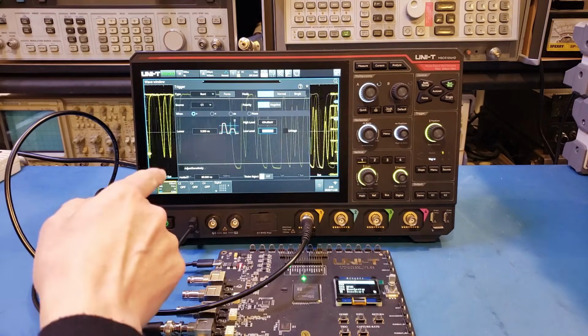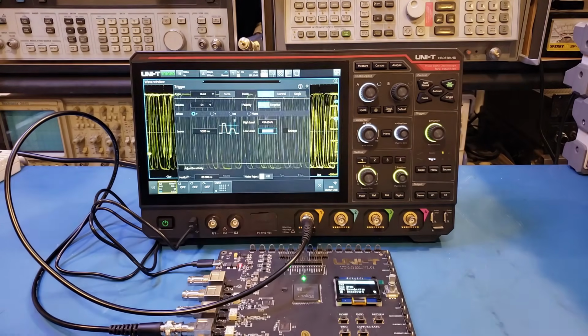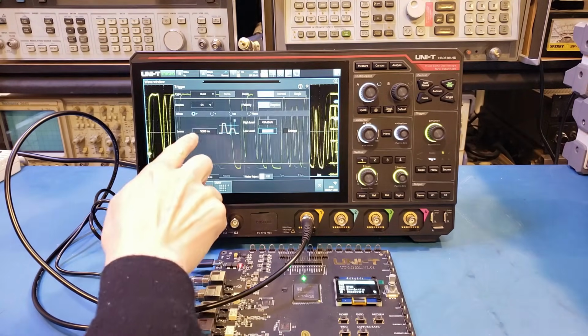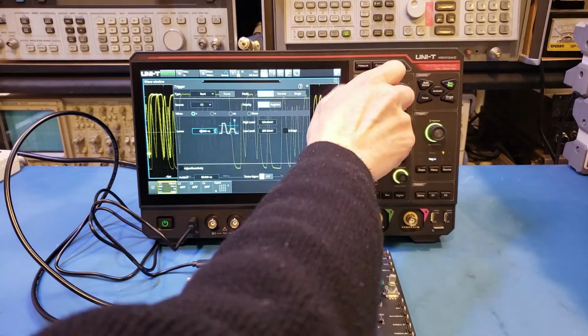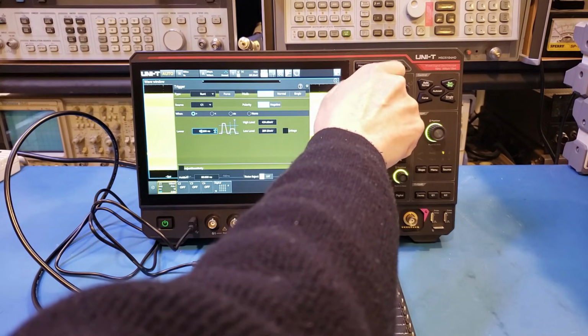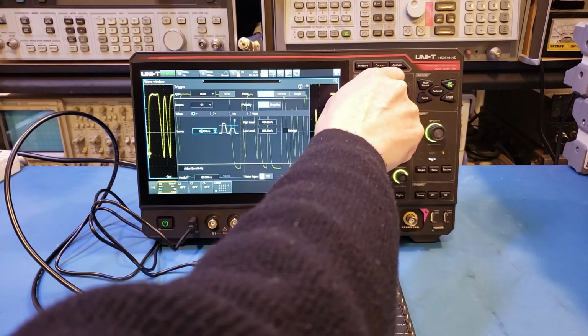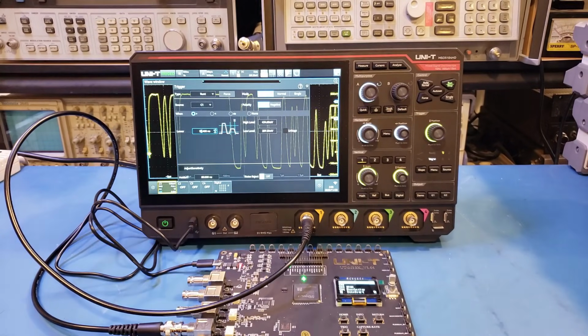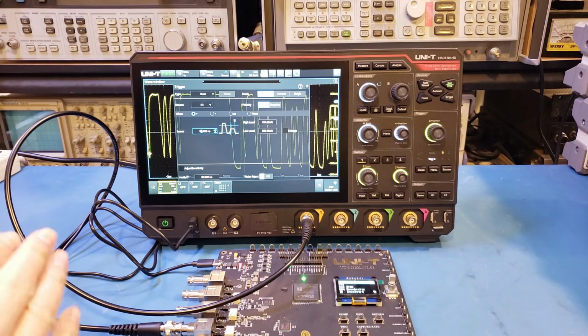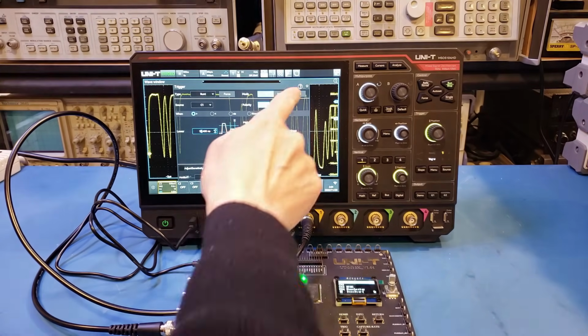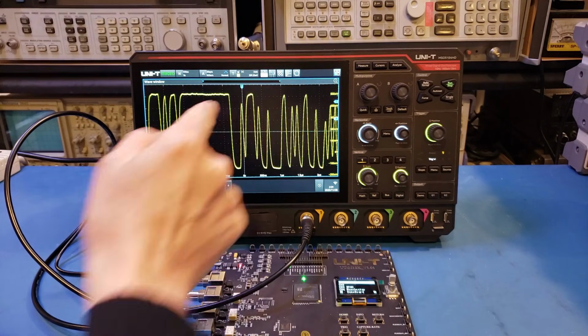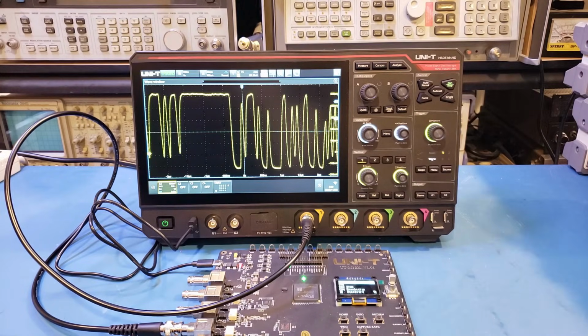Now we have the interval, and you can see here roughly per division is about 500 nanoseconds. So let's actually increase that. And you notice that at some point here, we actually are able to trigger it stably. So let's go back and take a look at the trigger signal. Of course, that's just a demonstration. And now you know how to trigger on the round pulse.